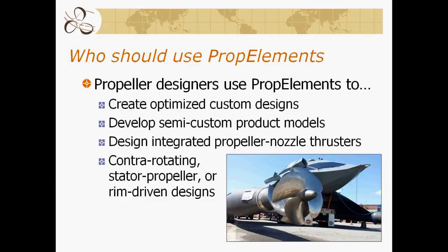Who should use PropElements? Obviously, propeller designers or consultants currently use PropElements for creating optimized custom designs, or semi-custom product models. You can create something that is not unique to a particular vessel. It's unique to a vessel type. What I mean by that is we can represent the inflow in the wake field by a particular radial wake distribution that's not specific to a particular motor yacht, but is representative of the family of twin screw motor yachts. Of course, the design of integrated propeller nozzle thrusters, or because PropElements allows for the calculation and use